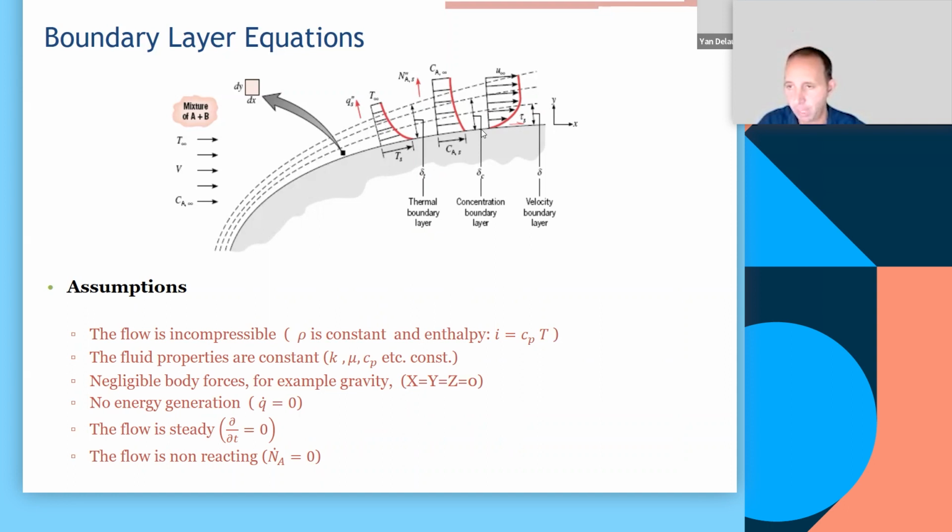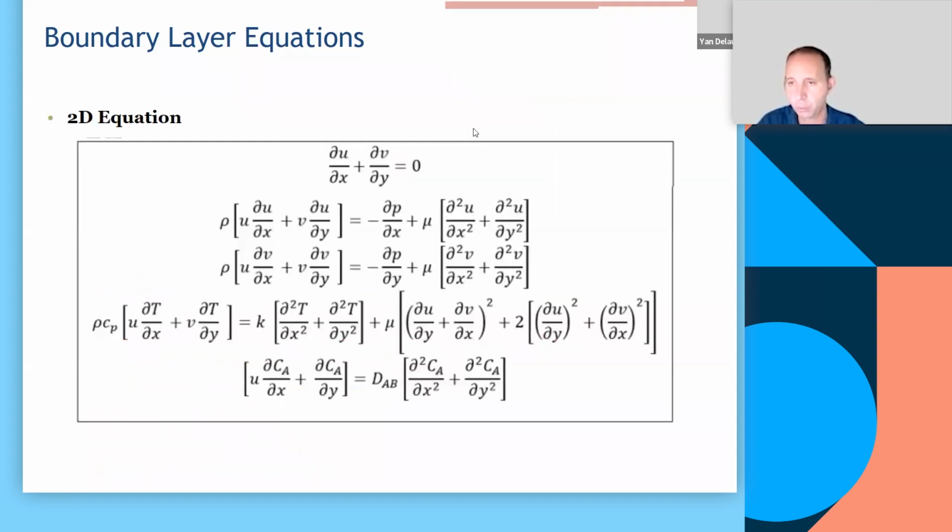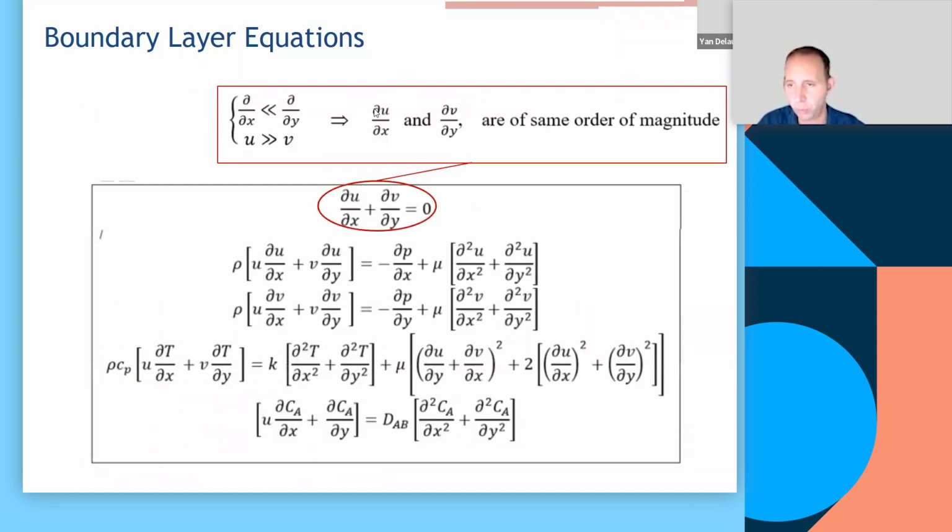That means there is some element of a y component to velocity, even though it's small. So we look at the relative importance of these two. When we compare these two together, we see that they combine one that's small with one that's large with one that's small. They are both actually of similar order of magnitude, and one cannot be ignored when they are present next to each other in the equation. So neither of these can be simplified. Continuity equation remains as is.